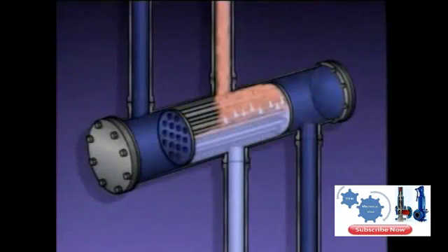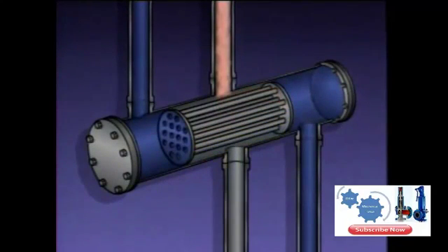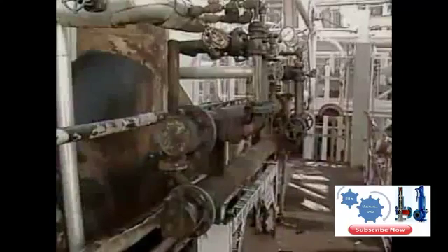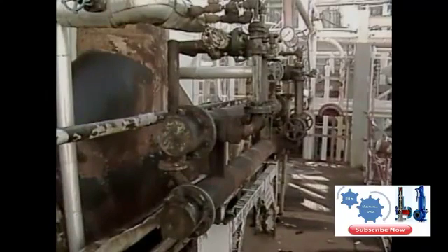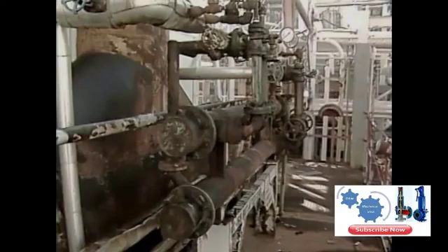Now, even though the low pressure inside a condenser is necessary for it to operate, it can also lead to some undesirable conditions. For example, there's always a chance that air will be drawn in through leaks or with the vapor flow. Air won't condense, and if it's allowed to build up, it can eventually fill the condenser and stop the flow of vapor. If this occurs, the condenser is said to be air-bound. To prevent this problem from occurring, air removal systems, such as an air ejector, are normally connected to a condenser.